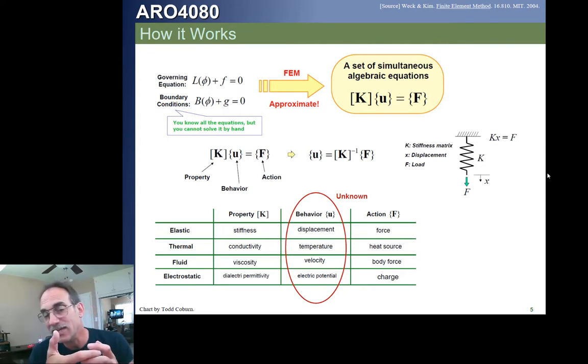Your software is then going to create a stiffness matrix. It's going to represent the stiffness of each structural element and then put it in a huge matrix that places all of the stiffnesses in relation to the others so we can see all the interactions between the different elements that are going to connect together. If you have multiple elements attached to a single point in your model, then each of those elements may contribute to the stiffness at that point. And the stiffness at that point is really a function of the stiffness of each element that's attached. So that's basically what it's going to do.